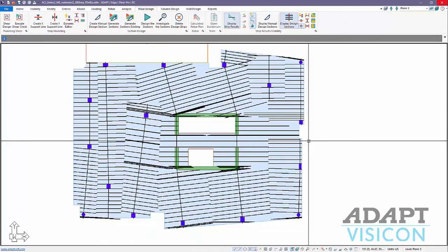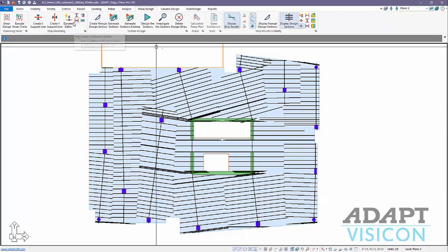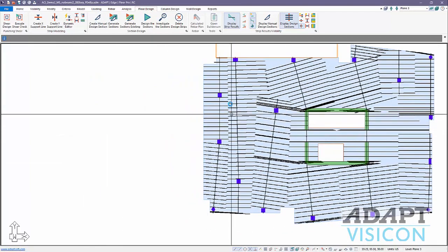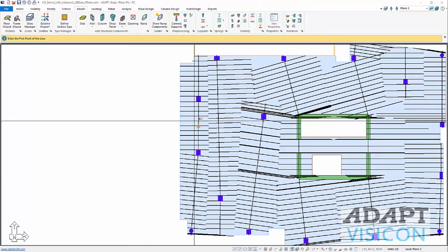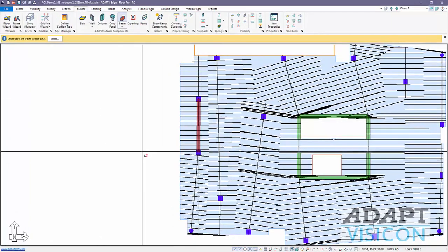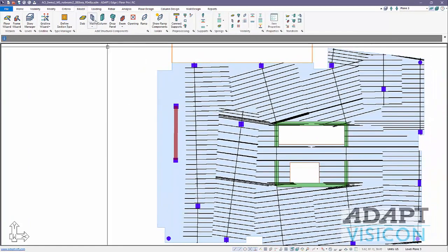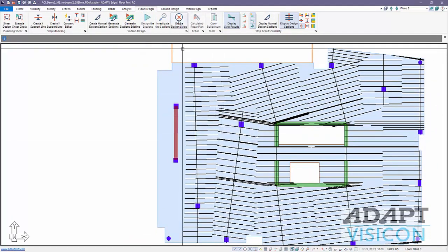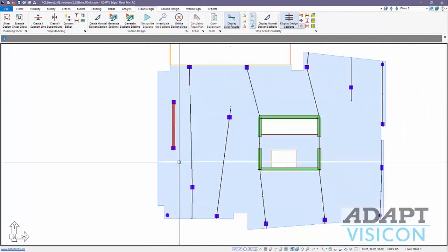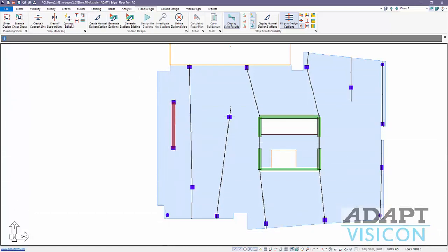One additional thing to point out regarding design strips is beams. How does the program treat beams when we use the dynamic editor to snap on beam locations? So we're going to add a beam along this line. I'll go over here to model and we'll just say I want to add a beam from point A to point B, and I'm going to delete this strip. I'll delete out the design strips for the model, and we want to talk about how is this beam treated using the new options for the dynamic editor.